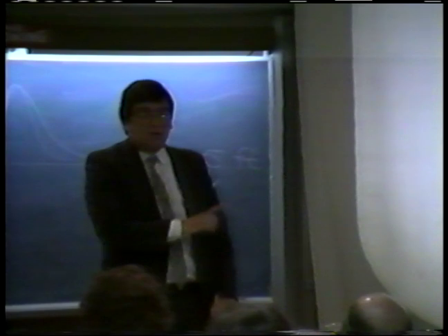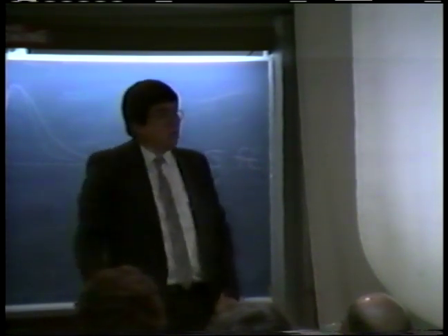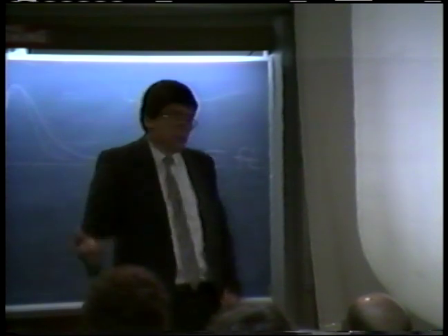And I'm going to have a chance to talk about that later on, the comparison between HEC-2 and HEC-1, and I know you already are familiar with that subject. I don't know whether I should stress that or not. But we'll talk about kinematic wave as the beginning of the analysis. If you really want to get into the analysis and understand what the kinematic wave does and how it compares with the dynamic wave and how it compares with the diffusion wave, which is exactly in the middle between these two.